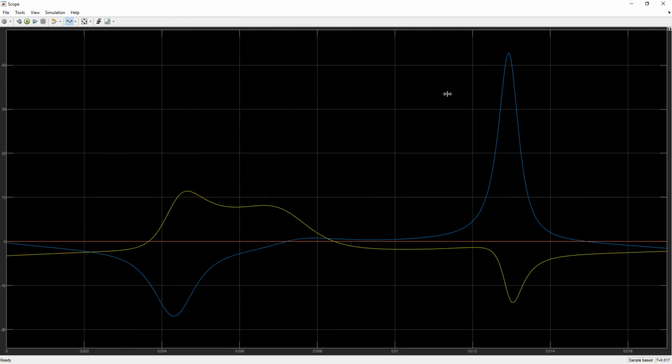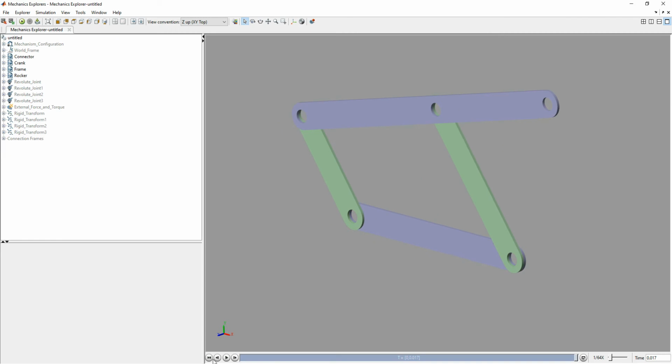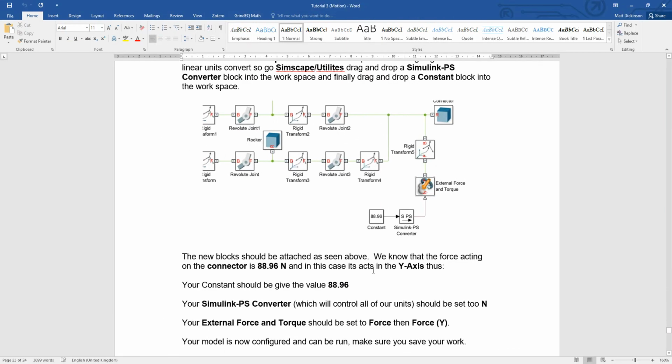So that would suggest to me, if we bought a motor which operated around 25% greater, so if we went for something like, just off the cuff, 60 to 80, if we went 80 Newton meter of torque for this particular body, we would be in good stead.